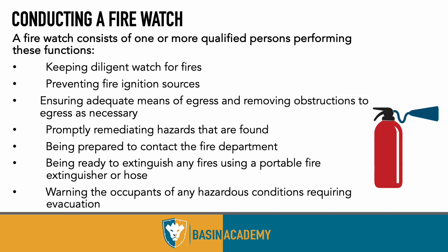When we talk about conducting a fire watch, this consists of one or more qualified persons performing these functions. So you should keep diligent watch for fires. You should prevent fire ignition sources. Ensure adequate means of egress and remove obstructions to egress as necessary. Promptly remediate hazards that are found. Be prepared to contact the fire department. Be ready to extinguish any fires using a portable fire extinguisher or hose. And be ready to warn the occupants of any hazardous conditions requiring evacuation.